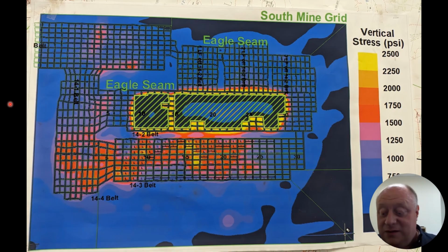It turned out that it was accurate, that it did increase the strength of the pillar, and that approximately 50% of that rock thickness you could reduce from the height of the pillar for your design. We'll get into a whole lot more detail about pillar design later on, but I thought I'd throw this in here as a nice example of a room and pillar mine where retreat mining was practiced.